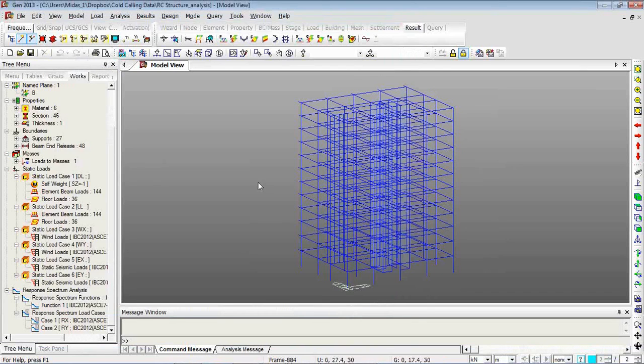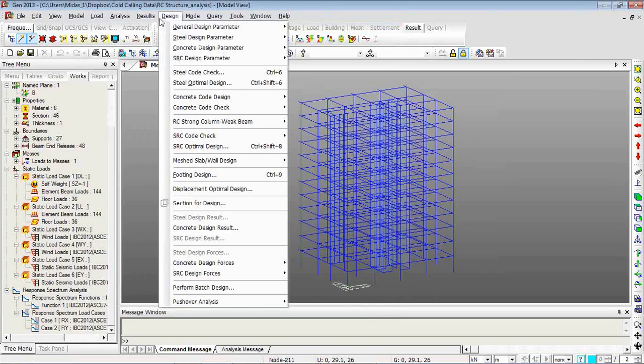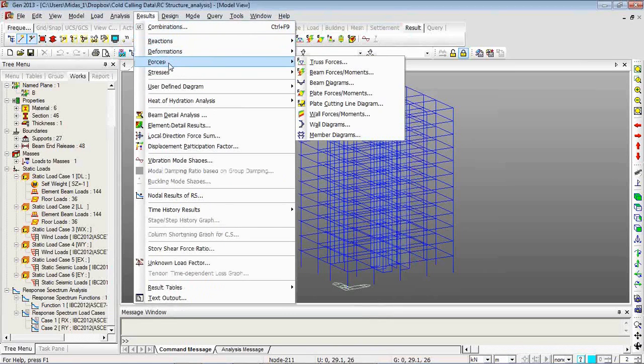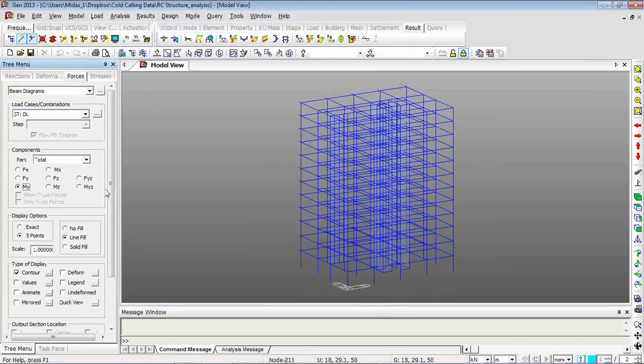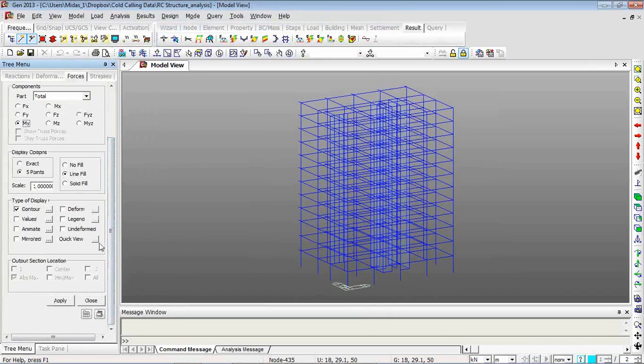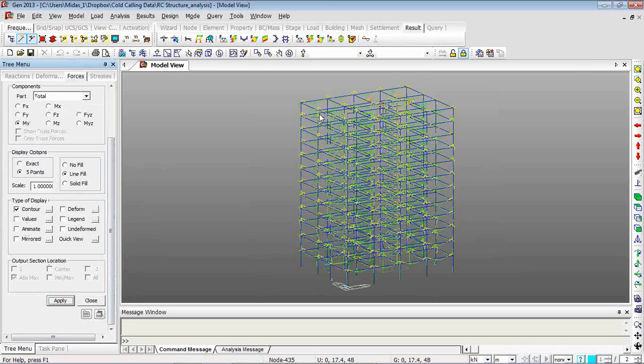So going to close. Now I will show you the results feature we have, beginning from the bending moment diagram. Let's say I want to check the bending moment available for 1B. So this is the general bending moment diagram, and I want to specifically examine. On your screen right now you will see the bending moment diagram for just the dead load cases